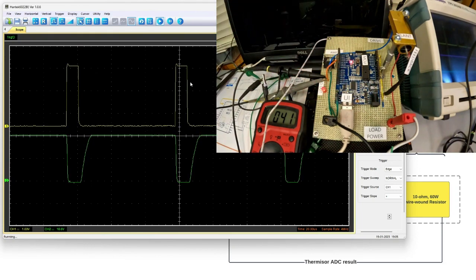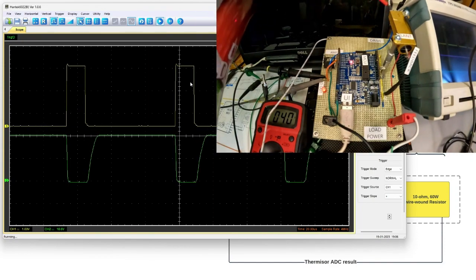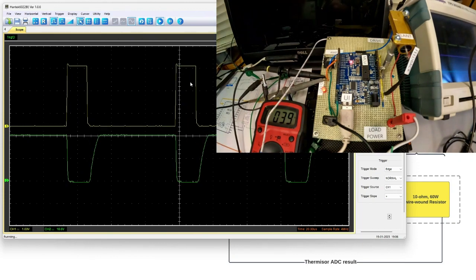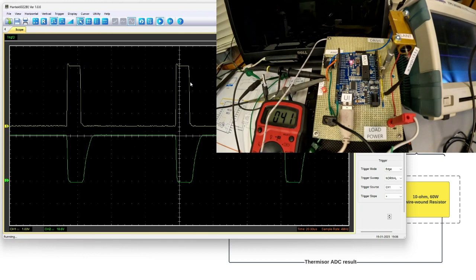So now you can see the scope and the video, and you're going to see a little tube come in, and I'll hit this with some air. And you can see that the temperature is going down, the pulse increased in width, and that's allowing a greater percentage of a period of the pulse width. The duty cycle, you can think of it as the percent of the period. The duty cycle went up.